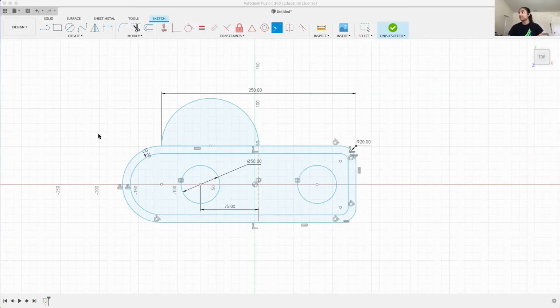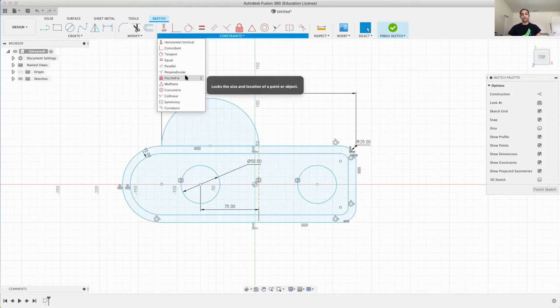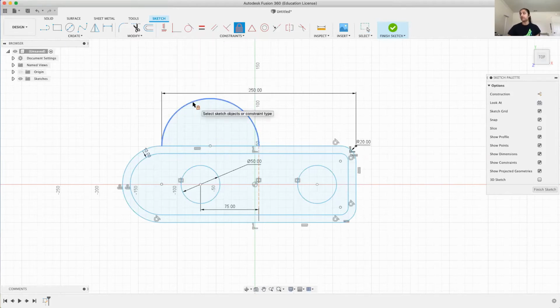So let's take a look back at our old design over here. So obviously Alan just explained all the constraints. Now, one thing I do want to show all of you is actually sort of the power of this fix unfix and the whole idea of fixing your dimensions. As Alan mentioned, when you fix the dimension of something, essentially what you're doing is you're locking that position and all the dimensions associated. So if I click this, you'll see it turned green. That means that I've manually fixed the object.